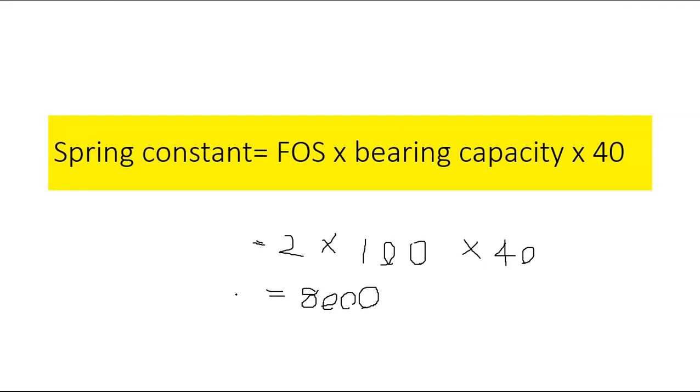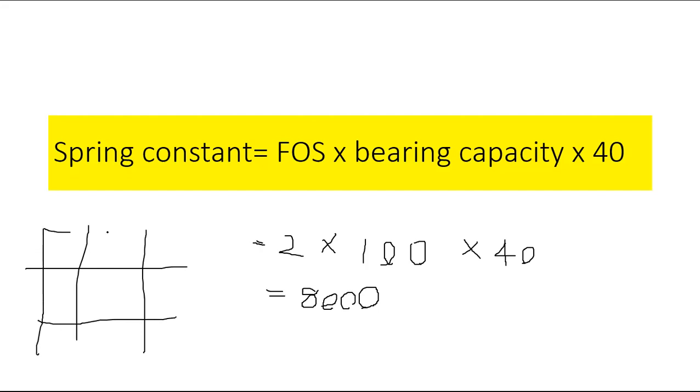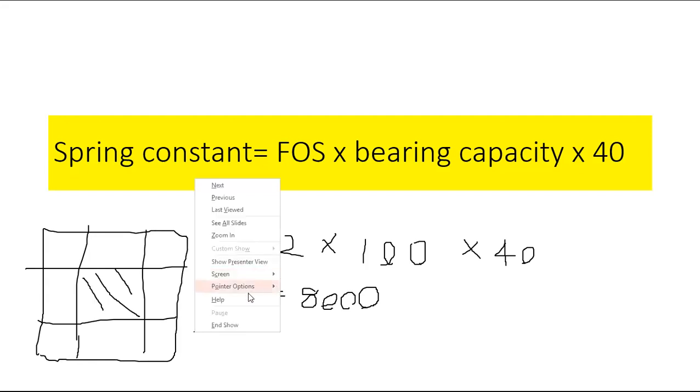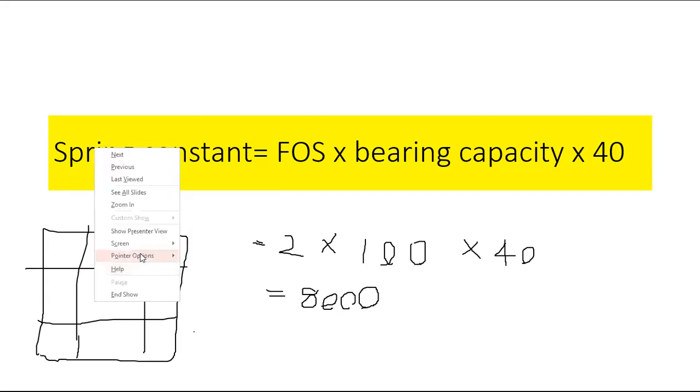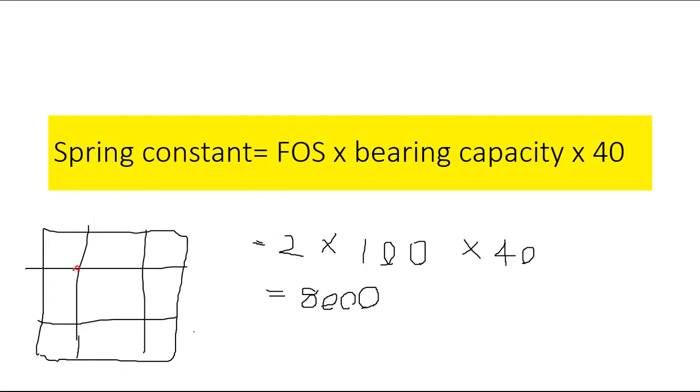So you need to multiply by the contact area. If you have something like this, it's like this. So this element, sorry, not the element. We are actually assigning at the joints. So this joint will have this tributary area, and so will this joint.